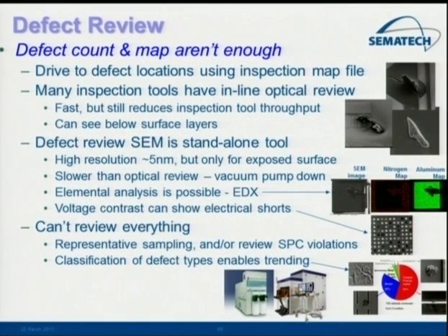If you looked at this and you saw iron and chromium, well, probably it's stainless steel. So this is a good way of being able to go and look at some of these defects, review it, and give you an idea, based on its shape and its composition, what the likely source of that defect is.